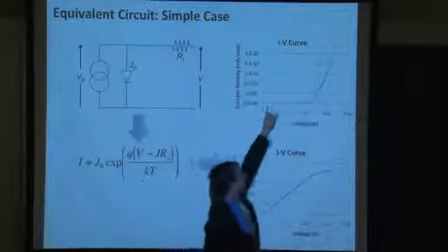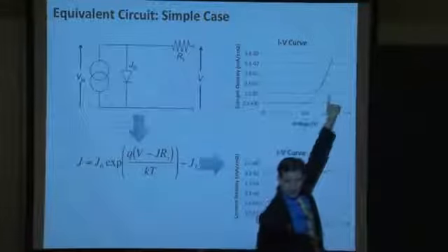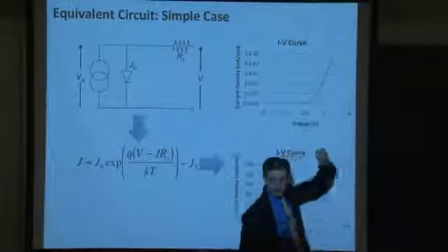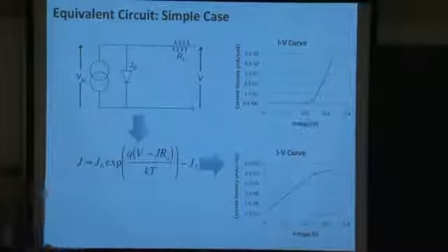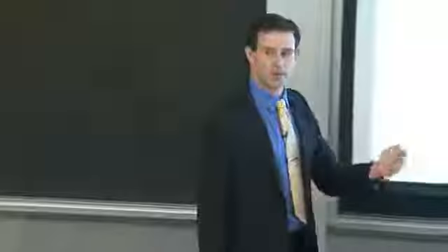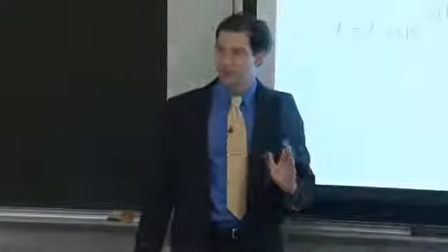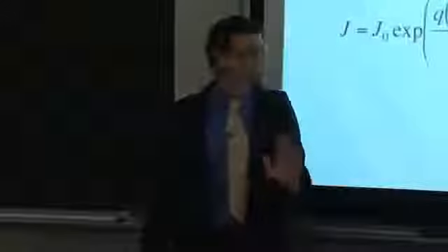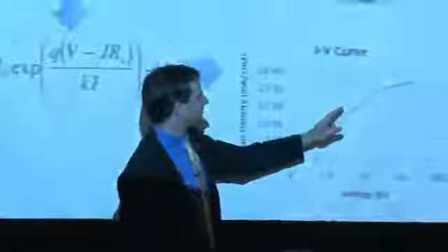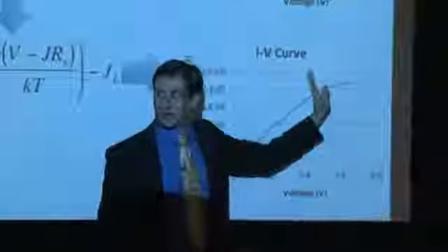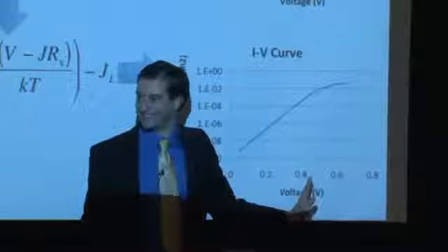The high current-to-voltage ratio only begins to take effect at higher voltages because of the exponential function of that curve. So that's a very important and astute observation, that the series resistance begins to kill you at high forward bias voltage conditions. You hope that you design your solar cell in such a way that the series resistance only really begins to kick in above the maximum power point voltage.